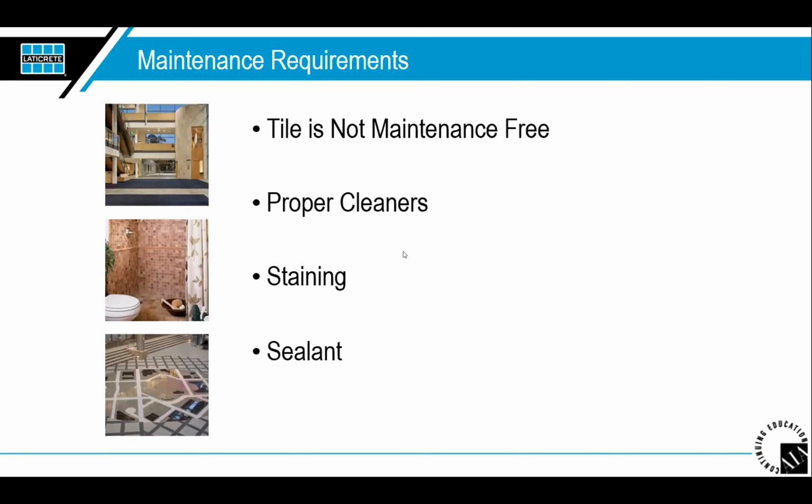We want grout to be as flush as we can with the tile, but when they wipe it with a sponge, which is inevitable, they have to do that, it's called dressing the joints. It creates a meniscus there. And if you're just mopping over the floor, what you're actually doing is cleaning the tile, but in reality, the grout joint itself is not being cleaned, and the dirty water is now sitting on top of that meniscus and is basically entering the grout at a very, very slow rate when it has a sealer put onto it.